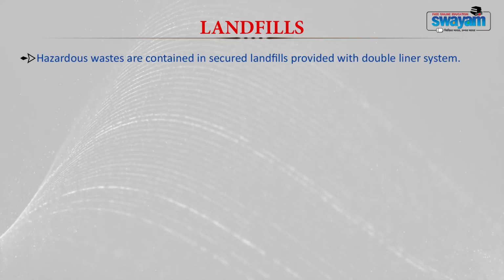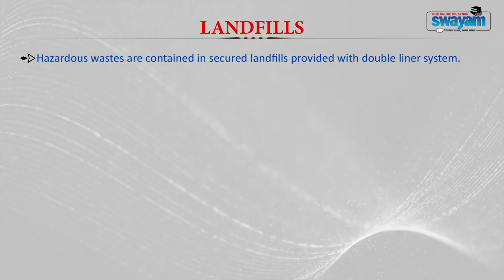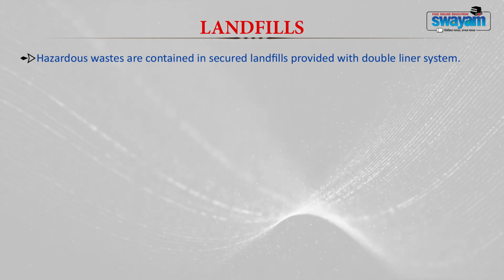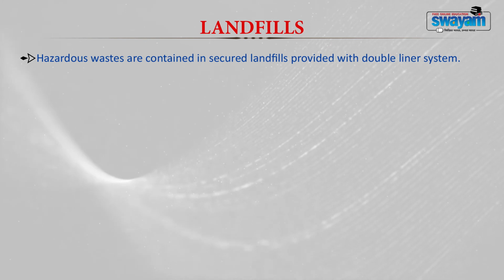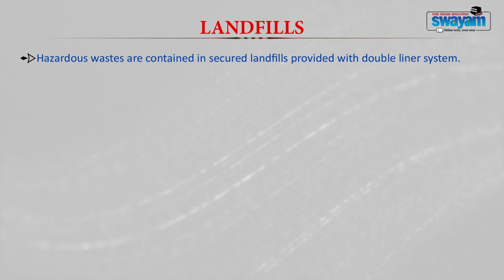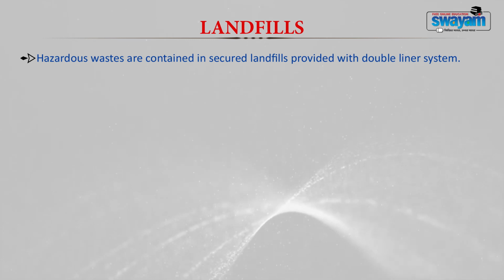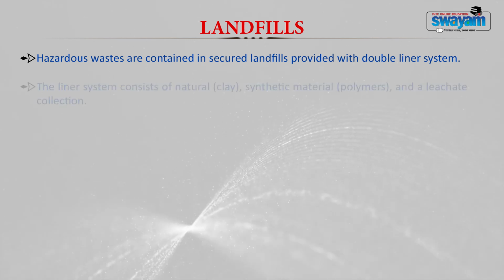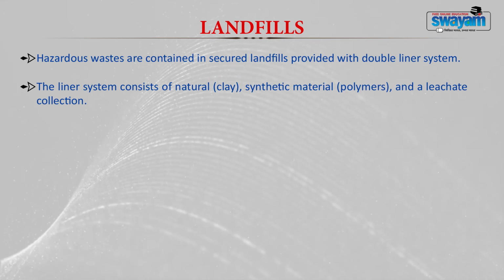Now, hazardous waste is contained in secured landfills which are provided with a double liner system. Again, as I told you, you have two different types of landfills: sanitary and secure landfills. Sanitary landfills are generally used for municipal solid waste and secure landfills are used for hazardous waste. Based on the liner system, secure landfills provide more protection for the hazardous waste, so you generally use a double liner system. The liner system generally consists of clay, synthetic polymers and a leachate collection system.